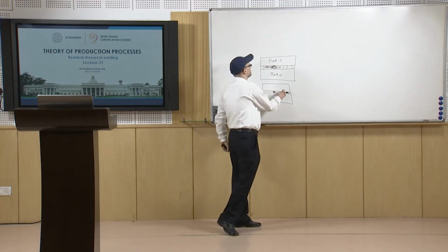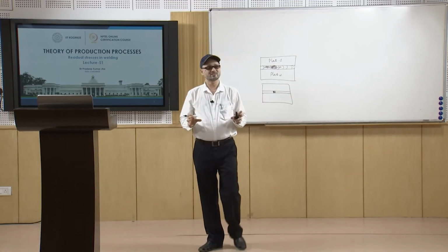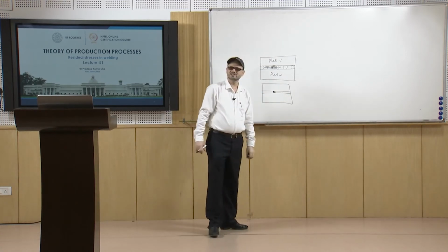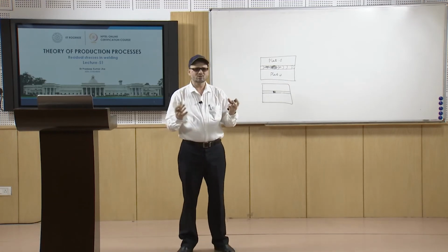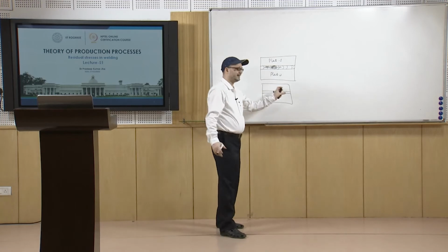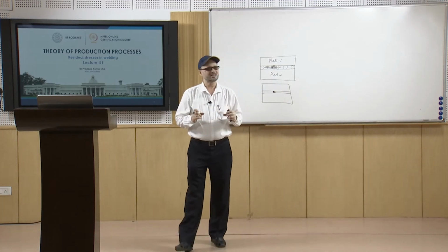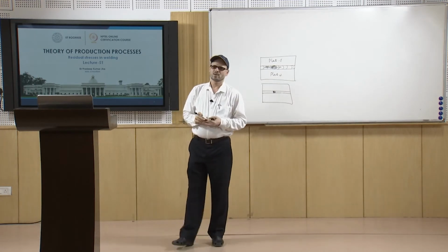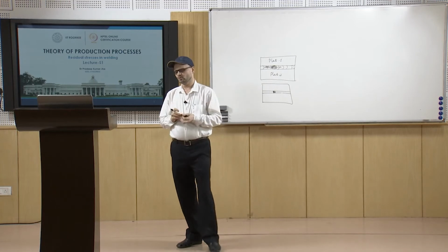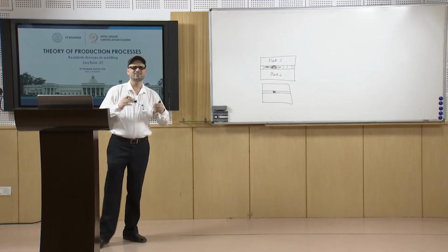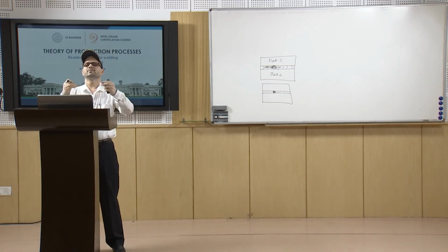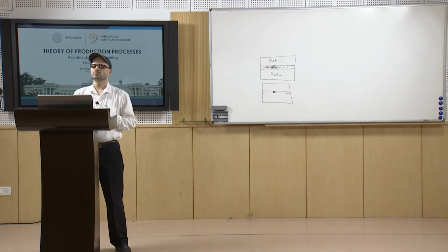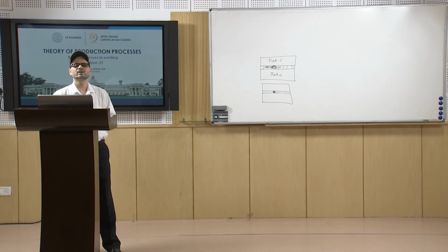Since they are not free to move, and there is expansion or contraction taking place because of the change in temperature, because once you have the welding going on, it will lead to an increase in temperature. Once they are trying to expand or contract and there is restraint from the sides, that will lead to the formation of stresses inside the body, because of this restraining action, and such stresses when generated are known as reaction stresses. So, you have basically mechanical stresses, metallurgical stresses, and also the reaction stresses. These are the three types of stresses.